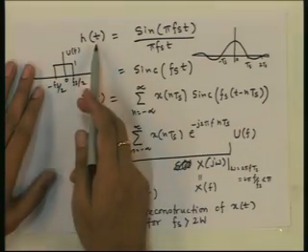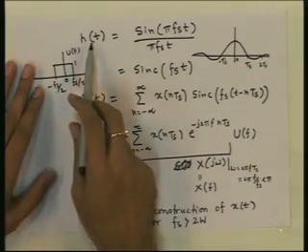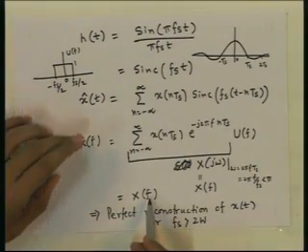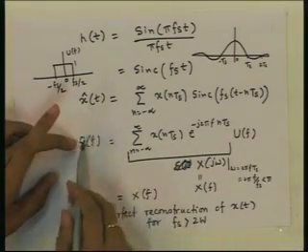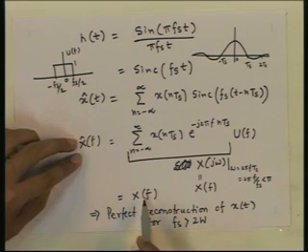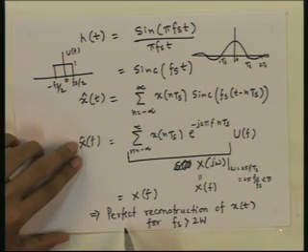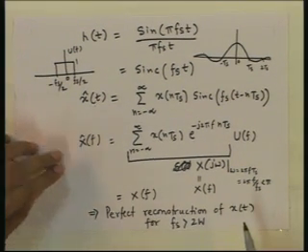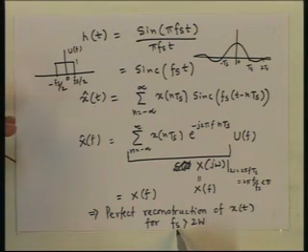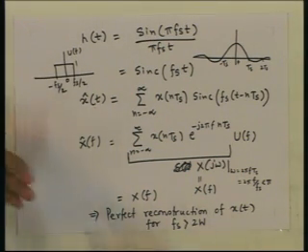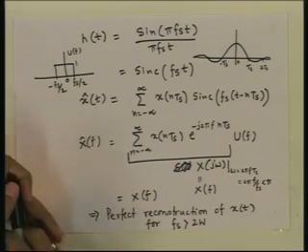After convolution we get the original signal, because in the frequency domain the spectrum of the output signal is same as the spectrum of the original analog signal. So, we reconstruct the signal perfectly from the sample signal, and this is possible because the sampling rate was chosen to be equal to or greater than 2W. Thank you.